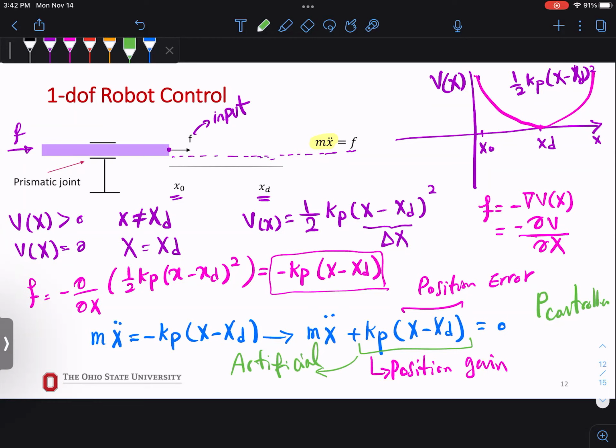That external force is being added to the dynamics of our system, so we can ensure that our end effector will cross the desired position at one instant. All right, so what is that KP? We need to decide how fast that is going, right? Depending on how big or small x minus x desired is, we can decide about our KP. We usually pick one and then draw and see how far we are. Then we change that KP until we find the desired KP value.